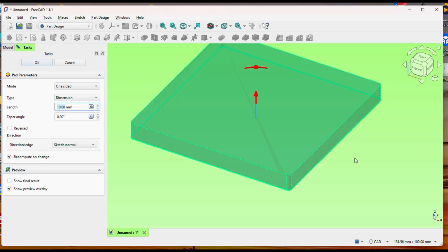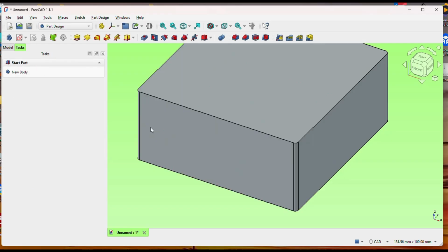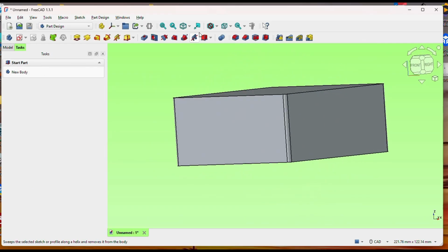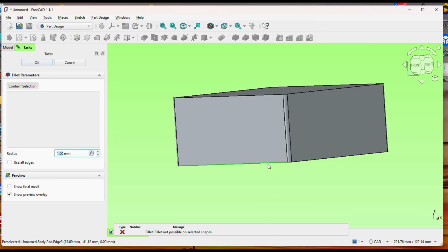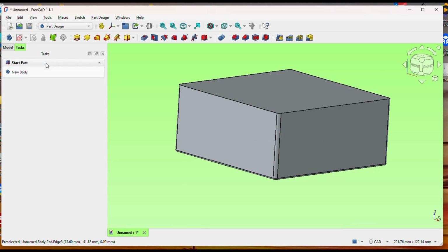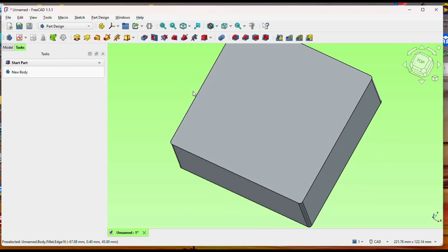Select that. And let's go up. I think you went about 45 millimeters. So we'll go 45. Say okay. And just on general principle, I don't remember if he had a small fillet here, but let's put a small fillet there anyway. Down here and select that. Since we got a fillet all the way around anyway, we'll make this just a 1 millimeter fillet like it's got here. Say okay. And then we gotta basically hollow this thing out.